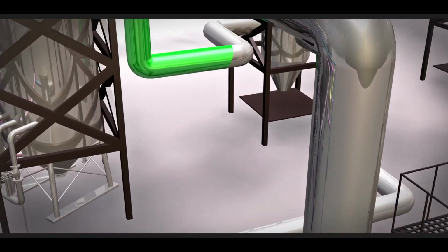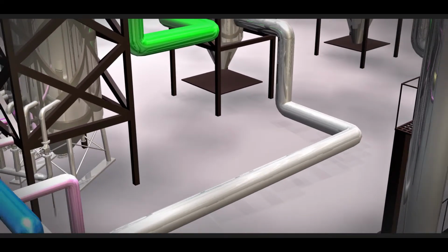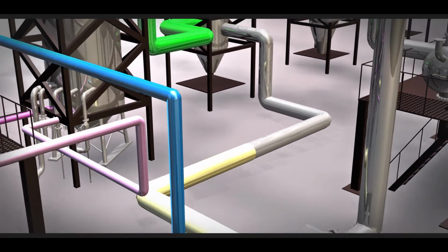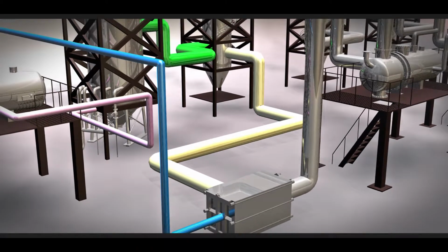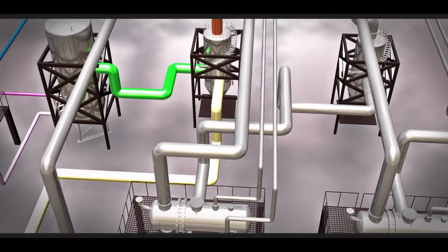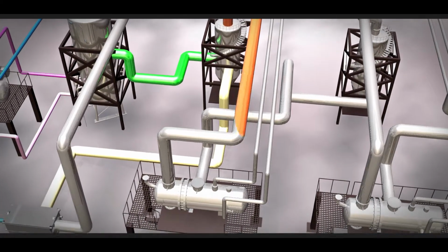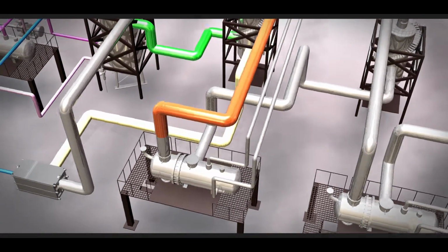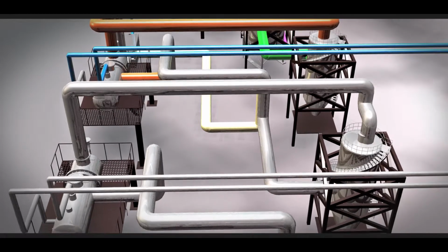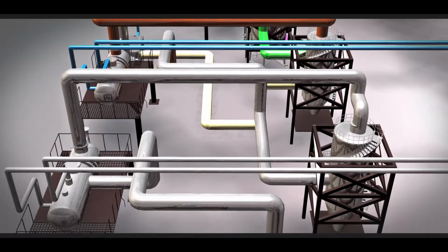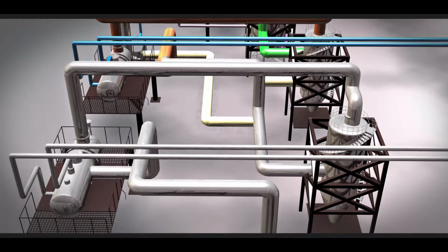The temperature of reactor 1 is about 300 C, and pressure is up to 20 atmospheres. The product of reactor 1 is divided into 2 streams, one enters reactor 2 and one is recycled to reactor 1 for better conversion and temperature control. Both the product and recycle are cooled in a heat exchanger to lower the temperature of reactors 1, 2 and 3.